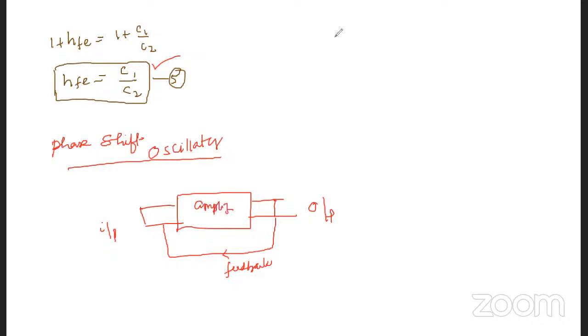The essential thing is that there should be a feedback of energy from output to input in proper phase to overcome the circuit losses and maintain oscillations. This can be obtained with the help of a resistive and capacitive combination, that is, an RC combination.